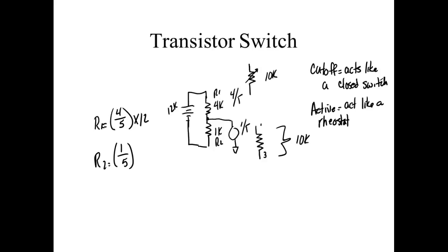So if you've got a circuit that you're putting different voltages on, and you're constantly recalculating I, you can use Ohm's law, right? V is equal to I times R, then you'd have to do that for every voltage. But this one here would always drop 1/5. This one right here would always drop 4/5. And if I knew that, I could put any voltage on there, and I could calculate the different voltage drops just like that, because all I have to do is multiply it times the ratio.